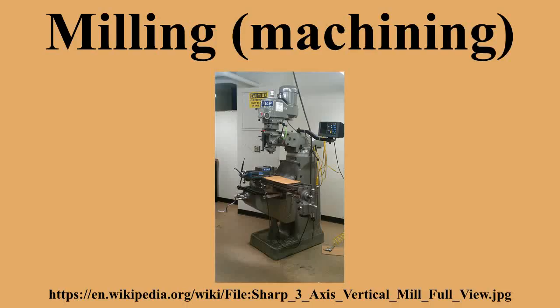A third type also exists, a lighter machine, called a mill drill, which is a close relative of the vertical mill and quite popular with hobbyists. A mill drill is similar in basic configuration to a small drill press but equipped with an XY table. They also typically use more powerful motors than a comparably sized drill press, with potentiometer-controlled speed, and generally have more heavy-duty spindle bearings than a drill press to deal with the lateral loading on the spindle that is created by a milling operation.